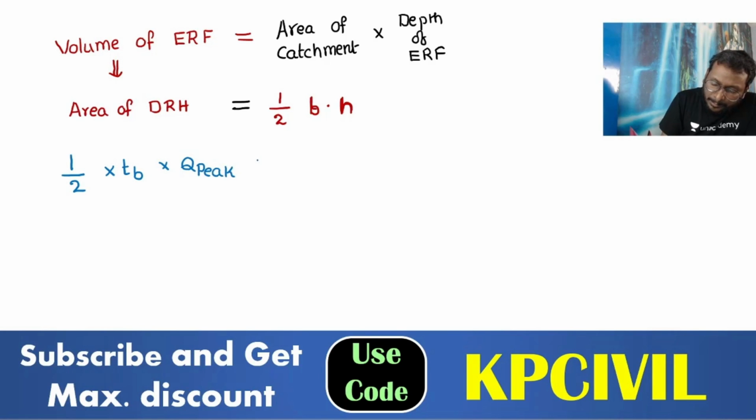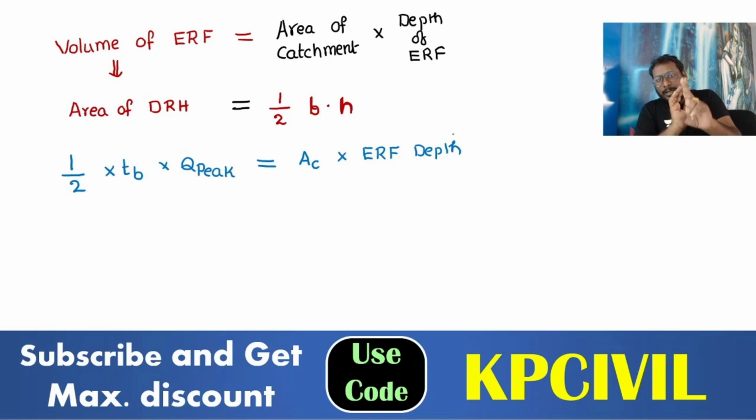Half into time base into peak discharge is equal to area of catchment into effective rainfall depth. I am going to equalize the volumes. Volume is obtained by two formulas. First one is volume from area into depth. Second one is volume from the area of the triangular direct runoff hydrograph.